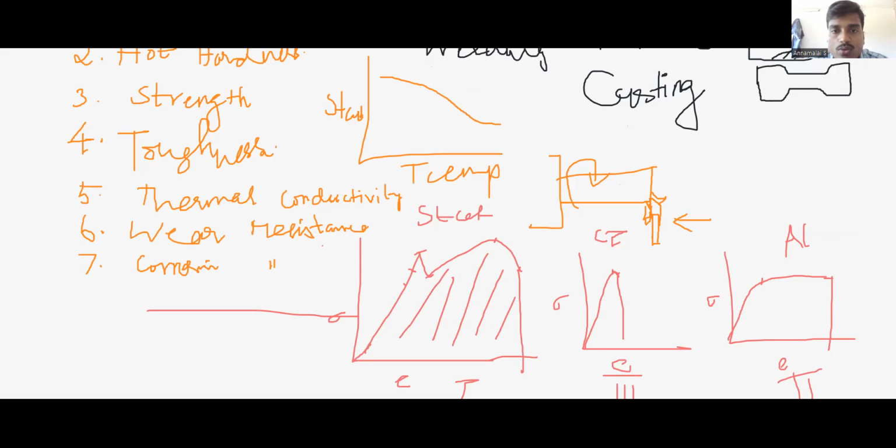If you apply a huge load on ceramic material, it will straight away break because ceramic materials are brittle. So we cannot expect a tool material to have all 7 properties. Some tool materials may have 6 properties out of the 7, or some may have 4 out of the 7. The tool material should have hardness, that is the primary property. It must have hardness. All other properties may be compensated by adding some kind of accessories.